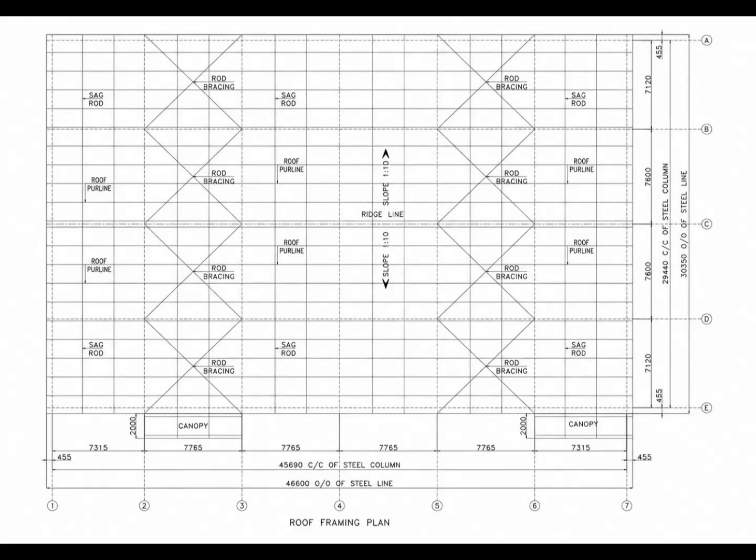But remember, this plan alone does not give us the complete three-dimensional picture. For that, we need to continue into the actual project model and examine how these members are physically positioned. So far, we have studied the sag rod from different 2D drawing views. We have seen its location in the framing elevation. We have now seen its location in the roof framing plan.